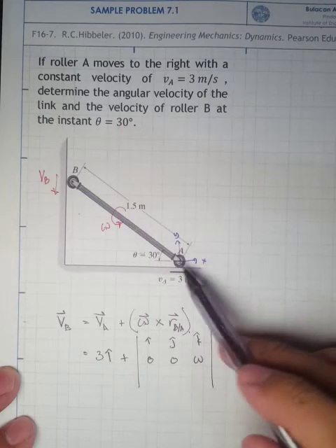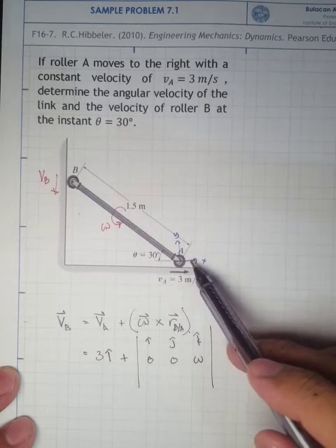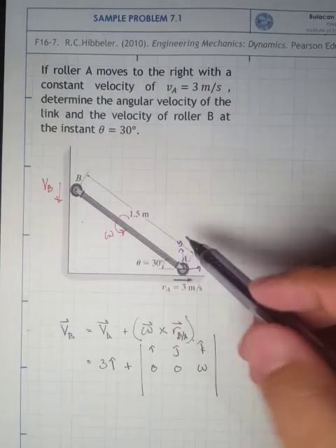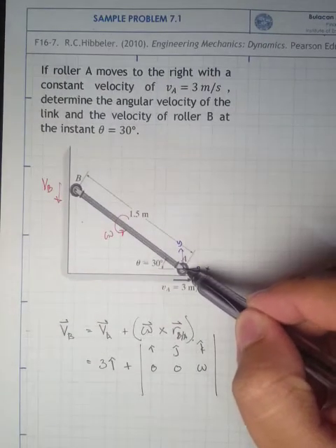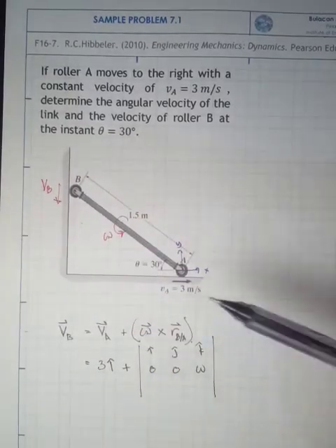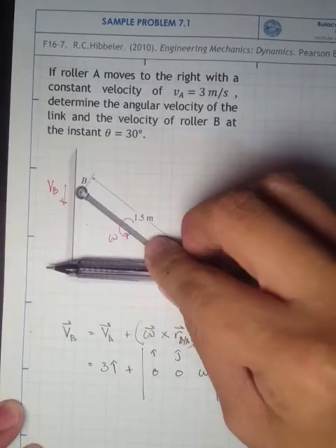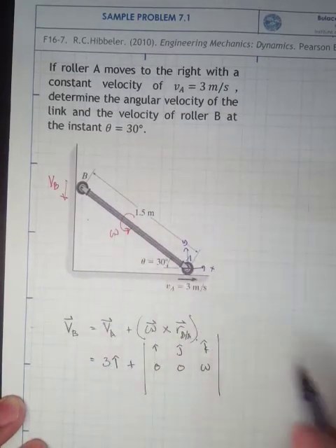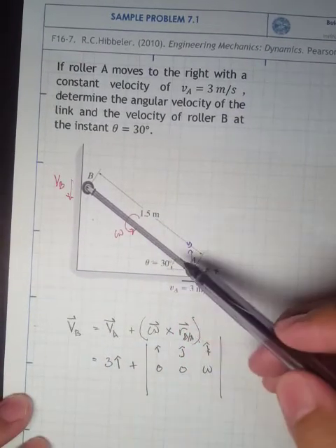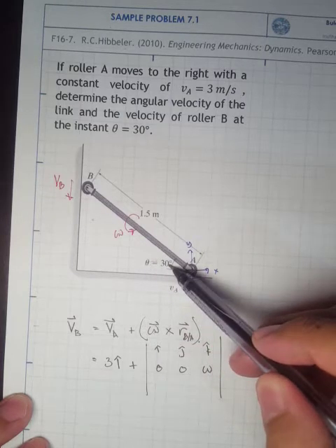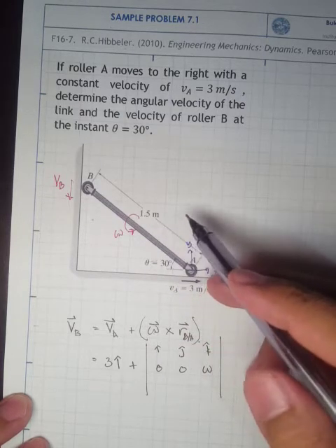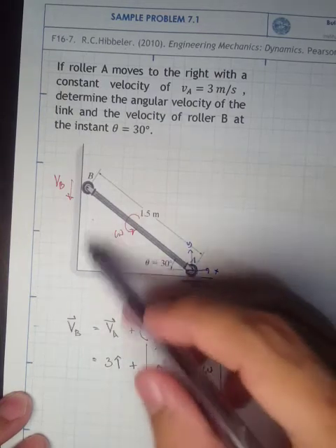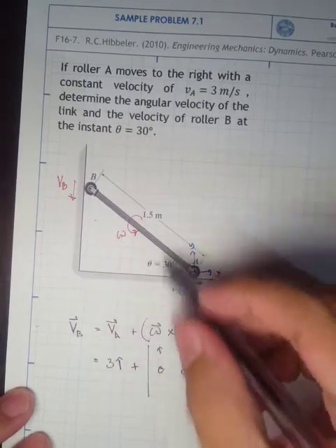We do a lot of changing of UCS. Here, from this point going to that point along the x-axis, we're going to the left, so we have a negative value here, but since we have this angle given and this hypotenuse, we can solve for the x component and the y component of the distance.